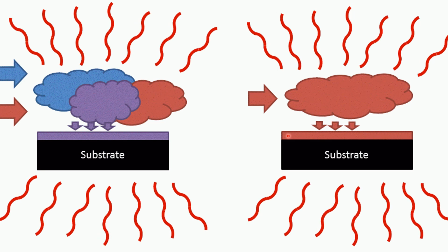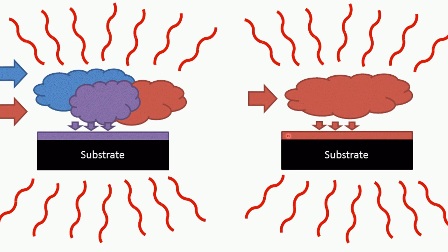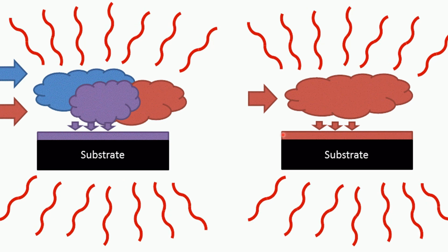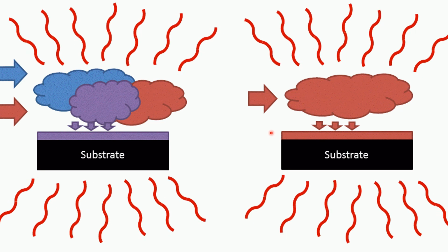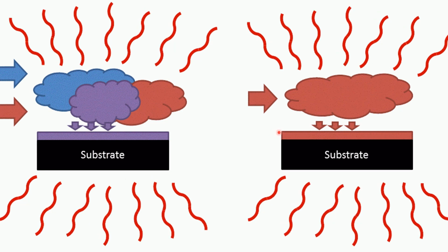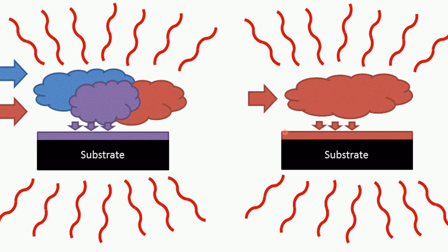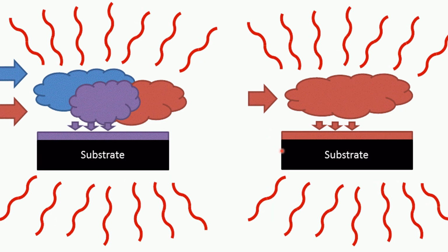Such type of chemical vapor deposition is known as pulsed chemical vapor deposition or controlled injected chemical vapor deposition. The pulsed or controlled injected chemical vapor deposition means that you can deposit a layer of different types of precursor material at different times.